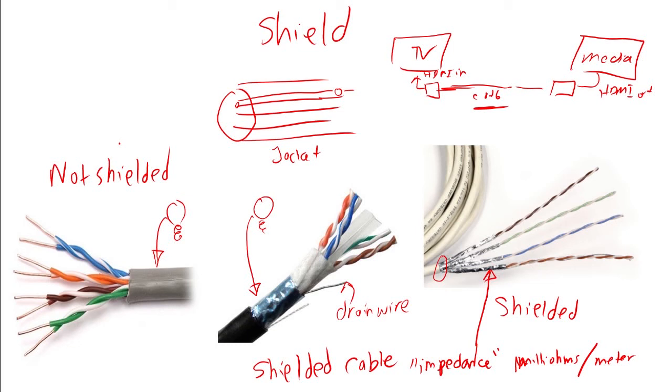Really the best type of shield is a big solid conduit made of metal. But conduit's not always possible. It's expensive. We may want to run our cable free air, and we may not have much noise.